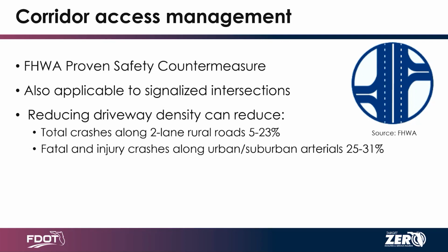What I mean by that is, as long as you can provide safe and reasonable access to a state road, it does not have to be directly on the state road. So side street access counts as that. Let's say there's a developing parcel and you've managed to secure cross access easements to the adjacent property owners. Then if a new person comes in, I do not have to give them access to a driveway. I can say you're going to take your access through your neighbor's parcel.